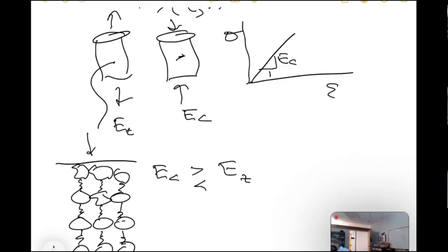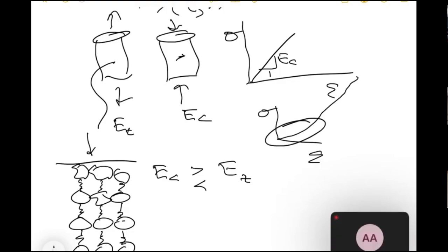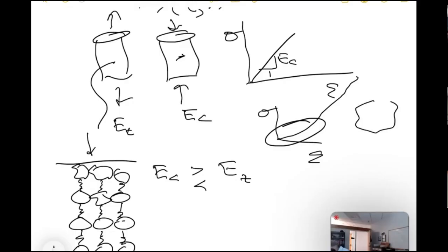What did I say about the granite? Do you remember when we looked at that stress strain compressive curve? It did this. It did a stiffening. Why was it stiffening? Because of the crystal rearrangement? Not for the granite. Nothing rearranged yet. That's for the granular material. Remember the granite crack closure. The granite has little cracks in it, and when you squeeze it, they start to close, which means it gets stiffer. So it does this.